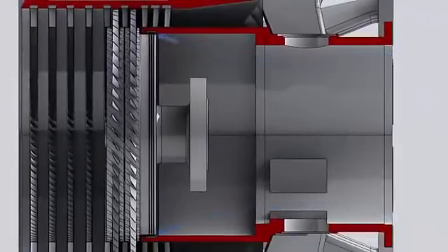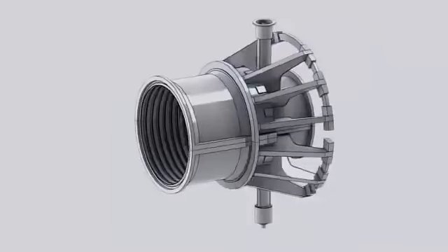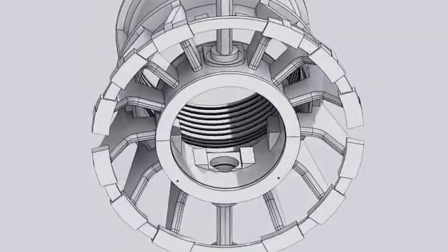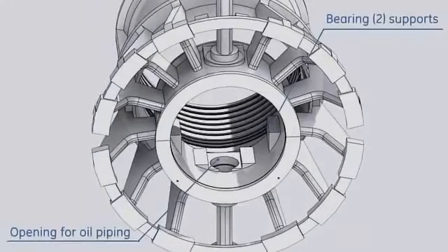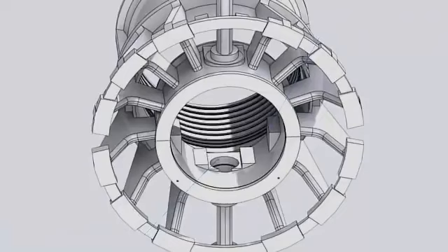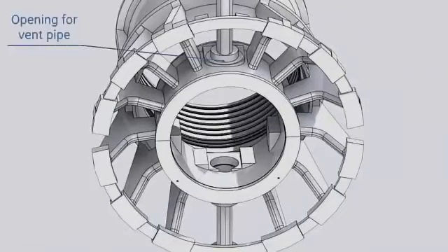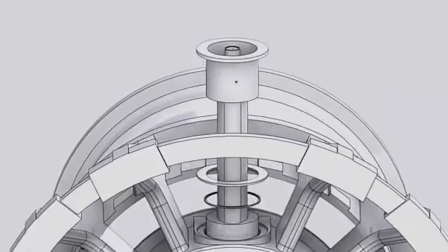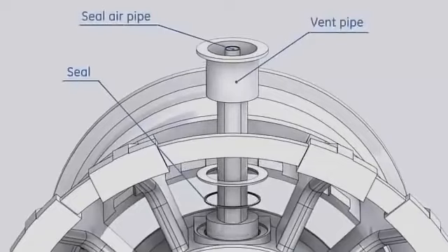The function of this arrangement is to control the amount of compressed air leakage inside the inner barrel. This air, despite being used to cool the first forward wheel space, the amount should be minimized to improve unit efficiency and minimize air leakage inside bearing 2 seals. The lower half of the inner cylinder supports the bearing number 2 and provides the opening for the lube oil supply and drain piping. The upper half of the inner cylinder has an opening for the vent pipe. Seals are installed at these openings to prevent compressed air from escaping inside the inner cylinder.